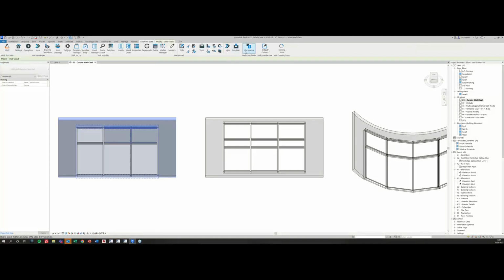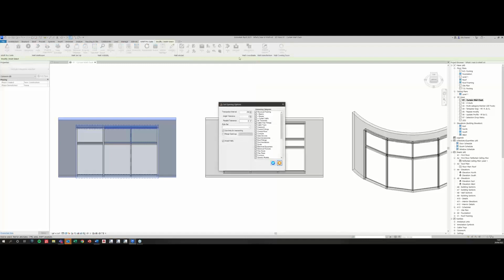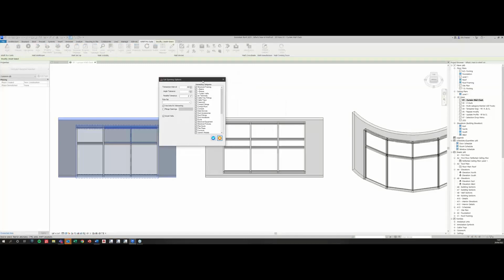So from here, I can go to the interference option and I can click on clash detection. Okay. So now within this menu, you'll see we have the usual options. So we've got transaction interval, which will run around 250 clashes before it has a break and then goes ahead to run the next 250. And you can actually set this between 0 and 1,000.